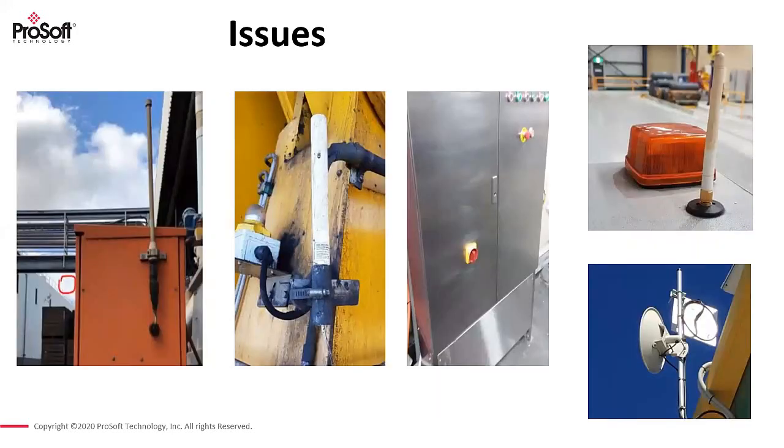Some other common mistakes. Here we've got the Omni again, communicating to an Omni in the distance. Now, generally antennas like clear line of sight, so they like to be able to see each other without objects in between. So that cable tray or bridge, whatever it is in the middle, that's an obstruction. It's going to interfere with the signal.